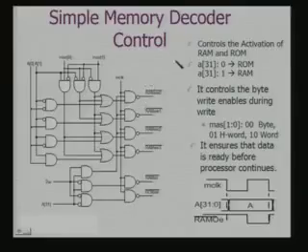The interesting thing to note is that I control activation of RAM and ROM. The A31 bit is typically used for this purpose. If you see here, the A31 bit is used for selecting RAM or ROM, obviously because they are located at two different addresses. They have to be located at two distinct partitions.